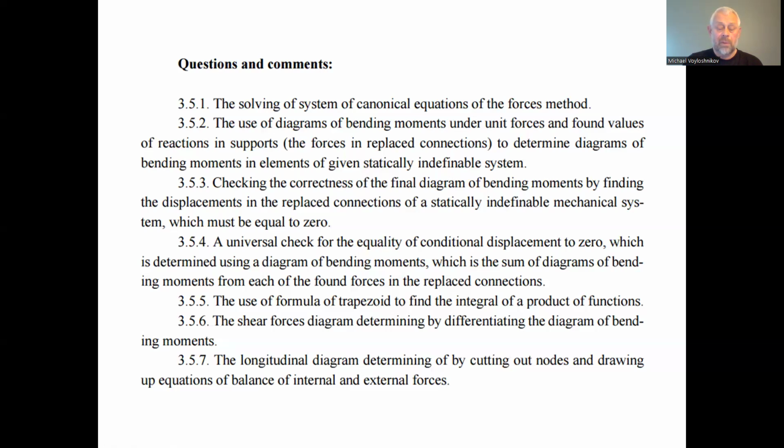To determine the diagram of the bending moment, after the decision of the canonical equations and finding the unknown variables, which are the support reactions in the cut-off supporting links, we can determine the diagrams of the bending moments and other diagrams, like the diagrams of the shearing transverse forces and the diagram of the longitudinal forces.